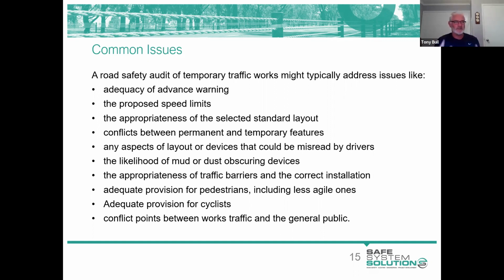40-kilometre-an-hour speed limits are for the safety of the workers. That's why it was introduced into the standard, and that's why we still have it. In South Australia, they have it at 25. And that's, to me, they're probably going to maybe another level again. But you talk to the real road safety engineers, and they'll tell you that 25 is a speed that, if unfortunately we're hit, you might survive. At 40, there's a higher chance you won't. So, 40 is certainly at the top end of providing the most safe environment. But that's the current limits that we are introducing. So let's use them to make sure it's for the worker safety.